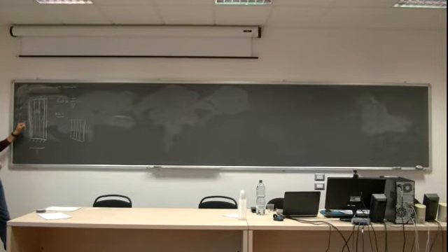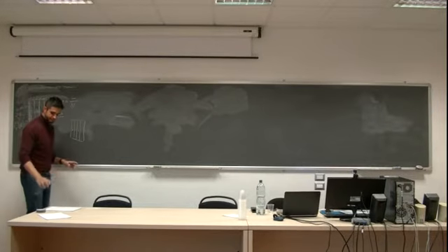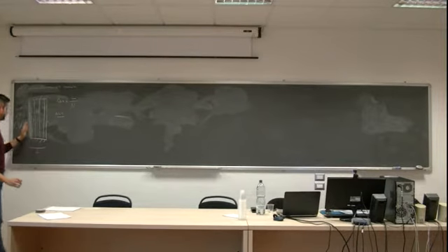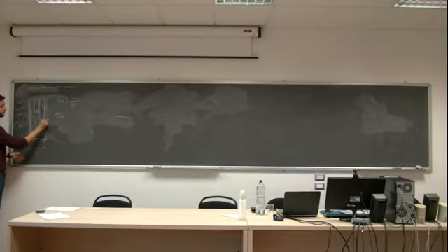Do you follow me? So, at the edges, the nodes are always half the thickness, or half the dimension, of the other ones. Okay? Imagine this node will have convection here and conduction going here, this node will have conduction and conduction, right? This also conduction and conduction, and the last one, convection and conduction. We'll face equations at the end. Energy balance we'll do later on.